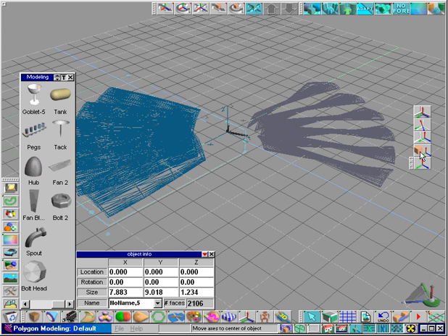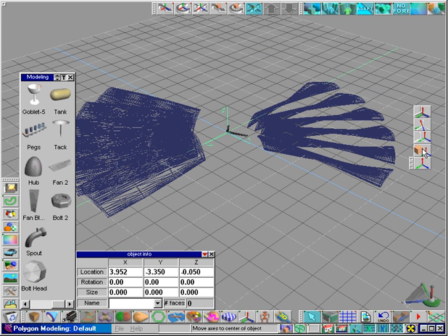Now select the first set and click on the Move Axis to Center of Object tool. Notice that the axis will move to the center point of the geometry bounding box. It is no longer at 0, 0, 0. Deactivate the axis. Boolean the 2 sets together. Click on the Move Axis to Center of Object tool and deactivate the axis. Since the geometry is symmetrical, the axis is now back at 0, 0 with some Z value.